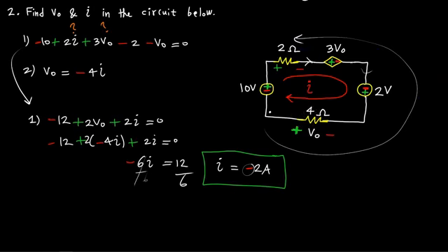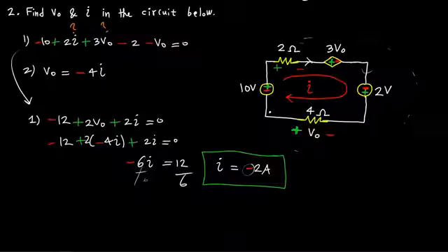But we can keep the same sign, we can keep the same convention and just keep carrying the math out. Or we could just flip it. We could flip the polarity or the direction of the current to the true direction and get this negative sign out of the way and call it plus 2A. But if we were to do that, we would have to change all of these equations and change the polarities for all these voltages. So it's up to you what you want to do.